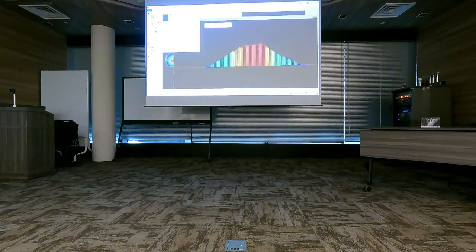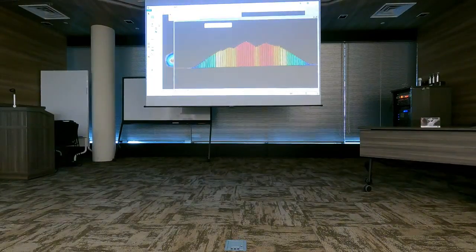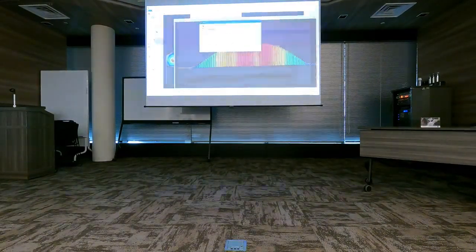So now I'm just using move section to see that everything is looking good. And this tool is usable when your ground surrounding the stockpile is relatively flat. It's an effective check method especially when the ground level of the stockpile is flat. But that's a quick demo of compute stockpile polygon.